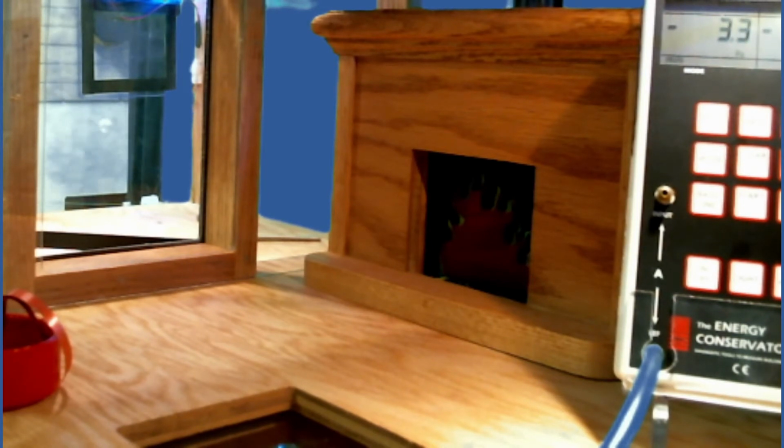And then when we do the air handler fan, we would go through the steps of checking the doors, and then we would do it once with the CAZ door to the house open and once with it closed. In this example I don't have that, but we'll do one in the basement CAZ, and we'll do that example. So right here, we're at -3. I'm going to turn the air handler fan on right now, and once we turn it on, we want to recheck the doors and see which is the worst case for those.